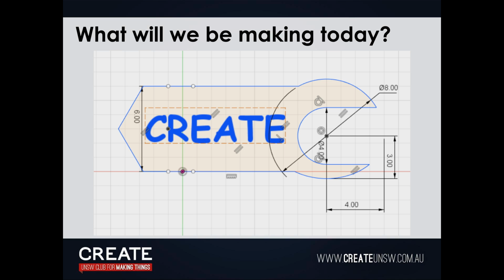Create, you can put your name on there, you can put your initials, doesn't really matter too much. That height, we'll put it as 8 mils. Once you're done, we're happy with that. We'll move those letters down a tiny bit. Let's just say 3 mil. Oops, -3. That's pretty centered. And that's pretty much it.